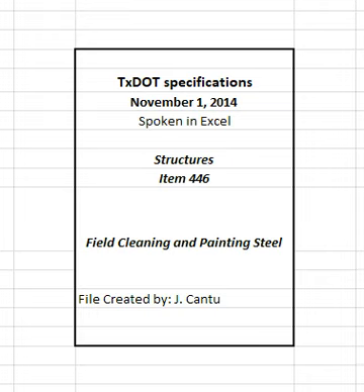4.7.4.7 Application. Clean steel surfaces or surfaces of previously applied coats of paint immediately before painting by blowing with clean compressed air, brushing, or both to remove traces of dust or other foreign particles. Wash the surfaces of previously applied coatings either with clean, fresh water or with a mild detergent and water mixture followed by a complete and thorough rinse with clean, fresh water when directed.